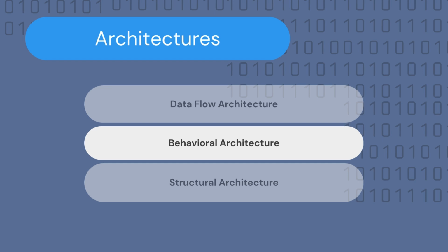The heart of the behavioral style architecture is the process statement. And this is the fourth type of concurrent statement that we've mentioned earlier in this video and also in our last video. As you will see in our future video, and briefly in this one, the process statement is very different from the other three concurrent statements. And the biggest difference is that within it lies sequential statements that are executed sequentially. The process will execute concurrently with other parts of the code, whereas the statements inside of this process are executed sequentially.